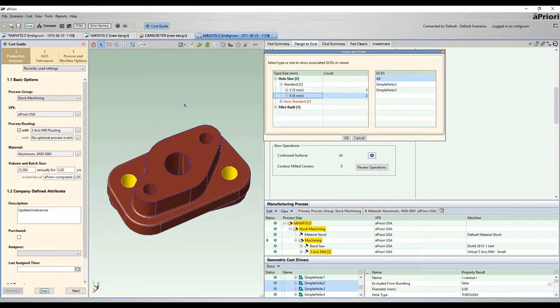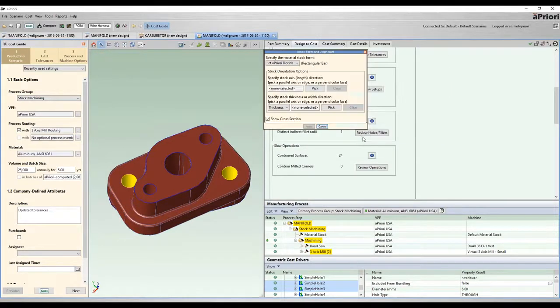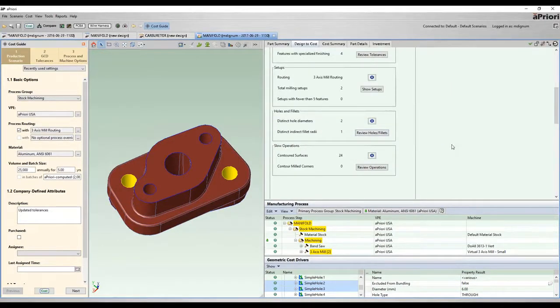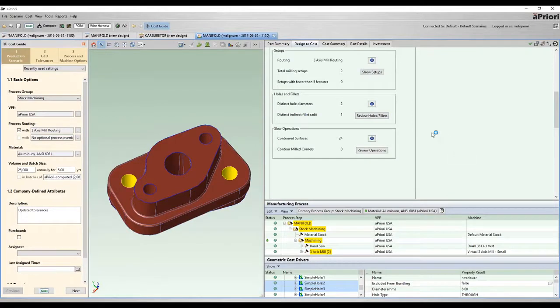These could potentially be consolidated into one hole diameter, but that would be a decision that I need to think about a little bit more in terms of the load that these individual bolts are holding and just the functional requirements on my part. So I'm not going to take any action here, but it's just some insight into what we're exposing.